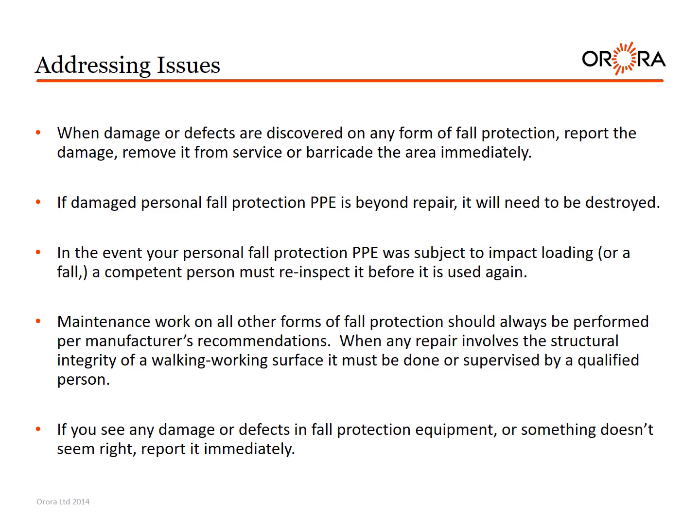Maintenance work on all other forms of fall protection should always be performed per manufacturer's recommendations. When any repair involves the structural integrity of a working surface, it must be done or supervised by a qualified person. If you see any damage or defects in fall protection equipment or something doesn't seem right, report it immediately.